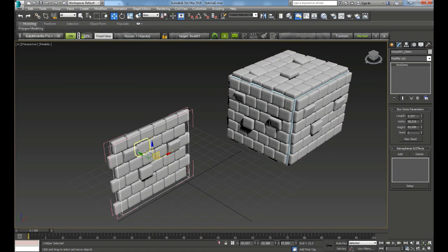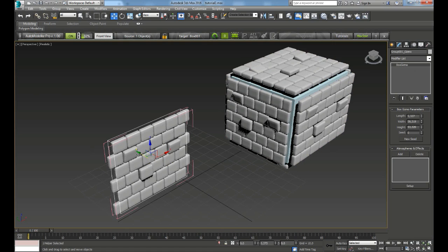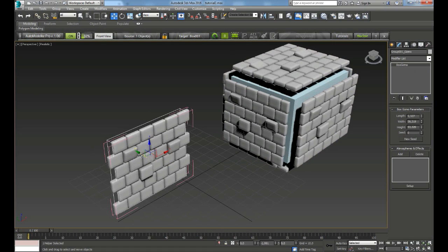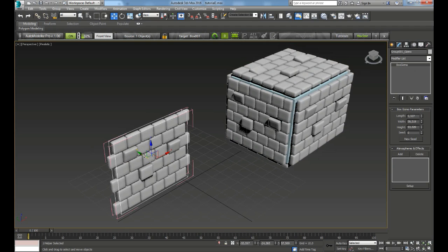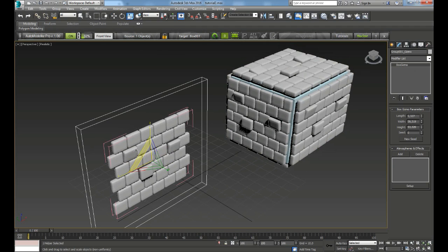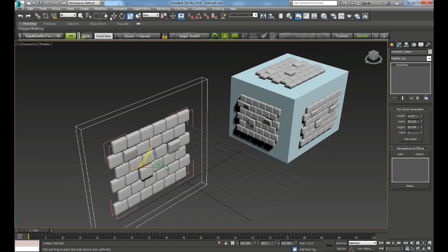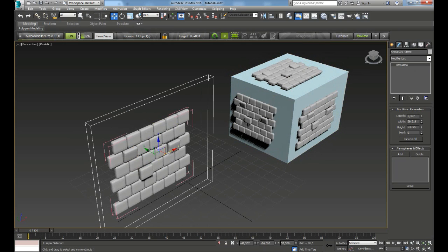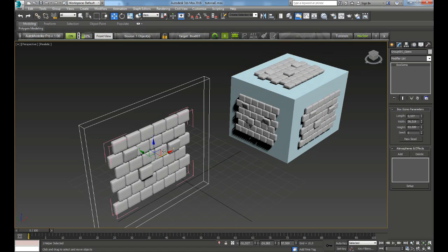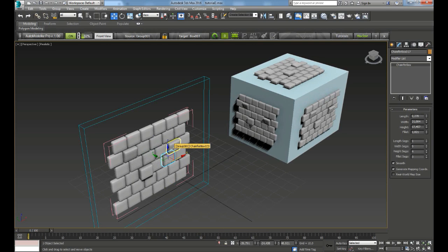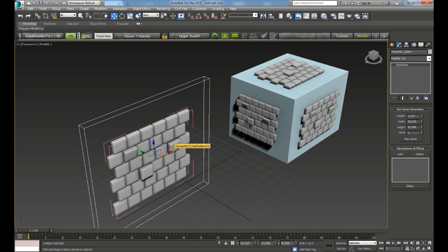It can also be used to offset the position of the geometry texture, or you can scale it. So this basically defines the part of the geometry texture that is going to end up on the target object. To quickly select the gizmo, you can select one object of the geometry texture and press Ctrl G. Then this is selected, which is useful.